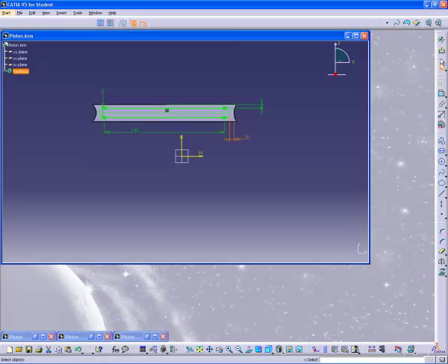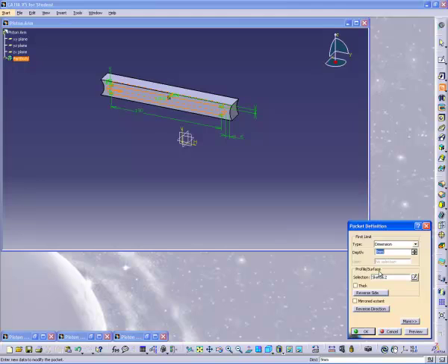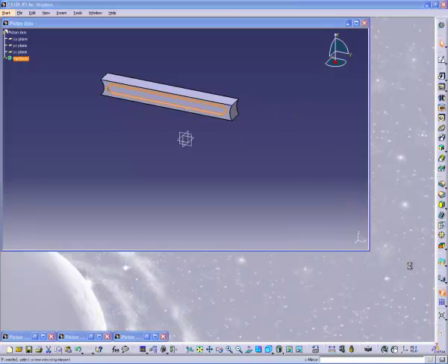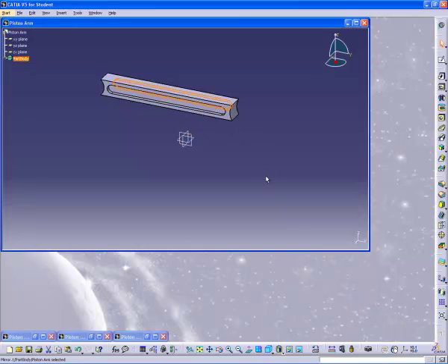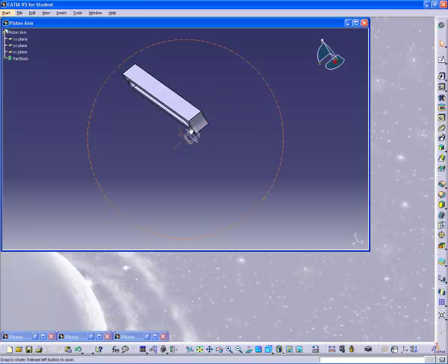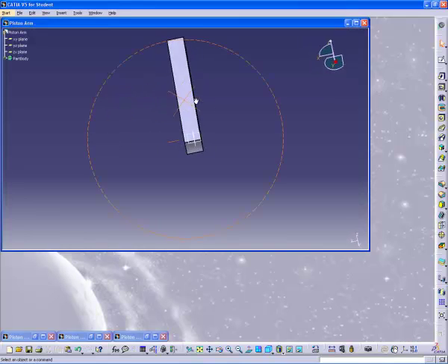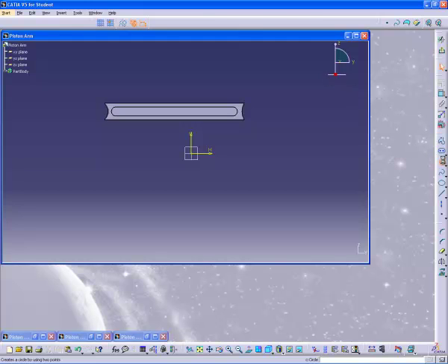Again, entering the Sketcher window in the YZ plane. Going to draw a hole. We're going to use a different dimension or constraint definition. We're going to make those two faces coincidence. We're going to then pad that circle, mirrored extent of 21 millimeters. Going to enter the Sketcher window once more, same YZ plane.